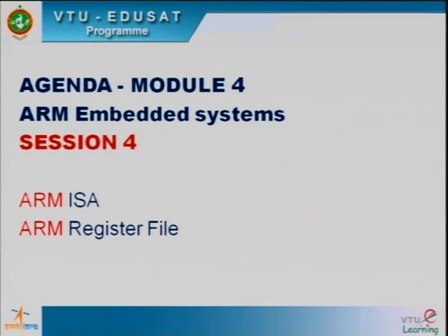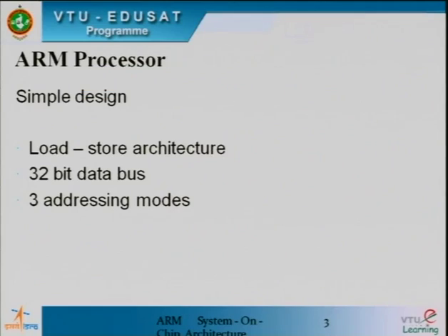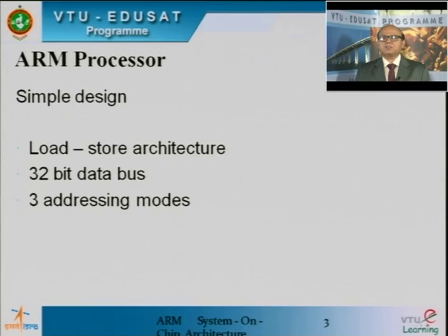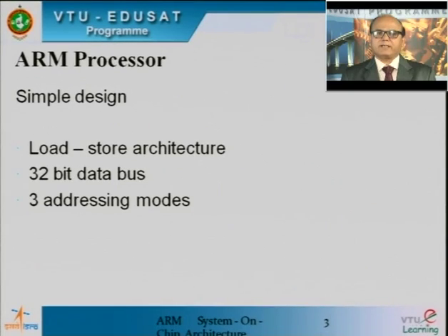Before we start discussing the instruction set architecture, let us recap what the ARM processor is. The ARM processor is a simple RISC architecture which adopts a load-store architecture. It is a 32-bit architecture, the data bus is 32 bits wide, and it supports 3 different addressing modes.